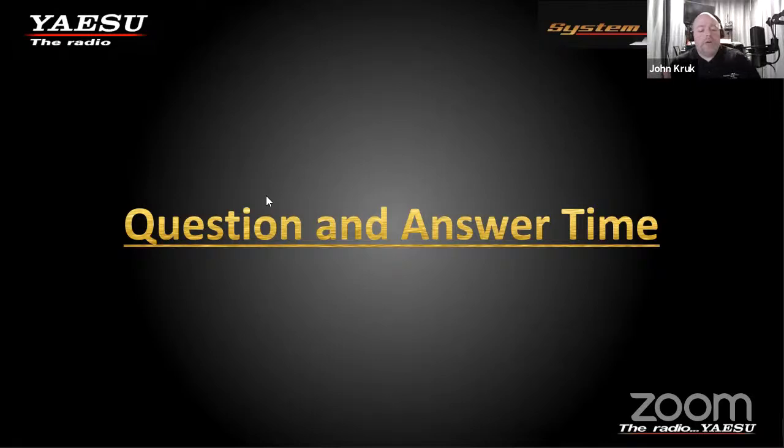Here's a good question: is there a way that a user on DG-ID 2 can tell that there's a user or conversation in progress on DG-ID 1? Yes, good question, thank you. Even though you have different DG-IDs, it's kind of like CTCSS. You'll see the signal light bar light up, and if you hit the monitor button, you'll be able to hear it like on analog. Same thing on Fusion: if you're on DG-ID 2 and someone's on DG-ID 1, your radio's not opening, but you'll see their call sign come across. Then if you hit the monitor button, you will actually hear that conversation. So, good question.